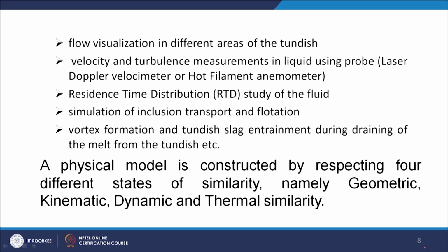Simulation of inclusion transport and flotation. That can also be done using physical models. You can make a model and have inclusions of different shapes and sizes, of different material, which can float inside the liquid. Accordingly, you will have to take the density of the inclusion into account, to see how they are transported to different regions of the tundish and how they float up. These can also be predicted.